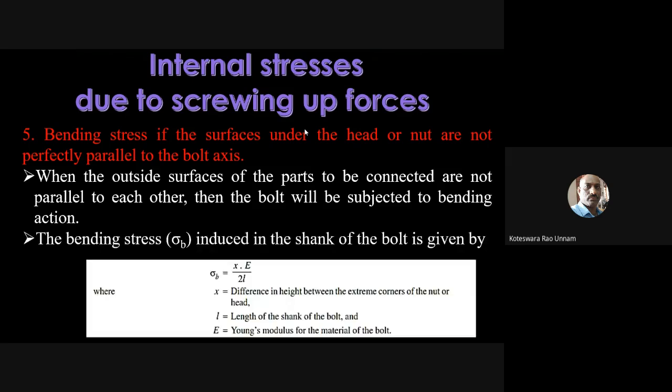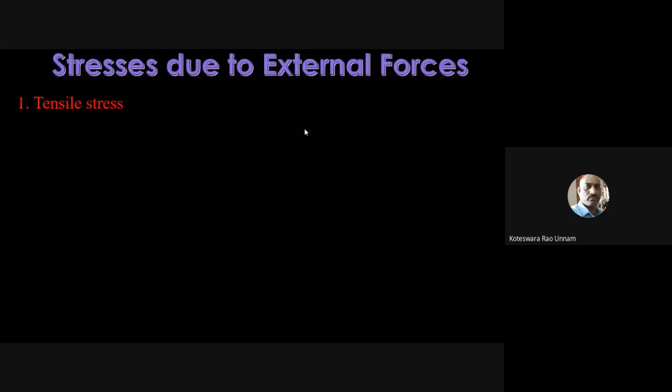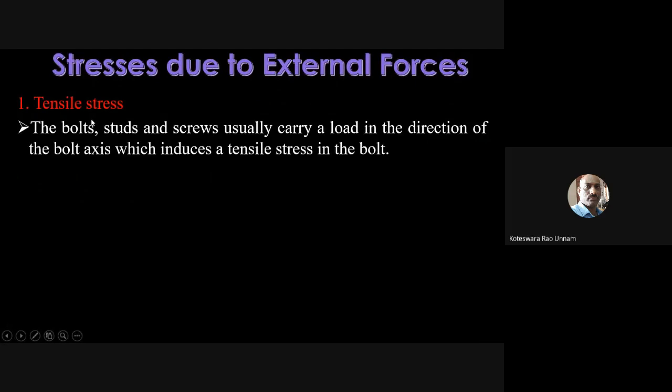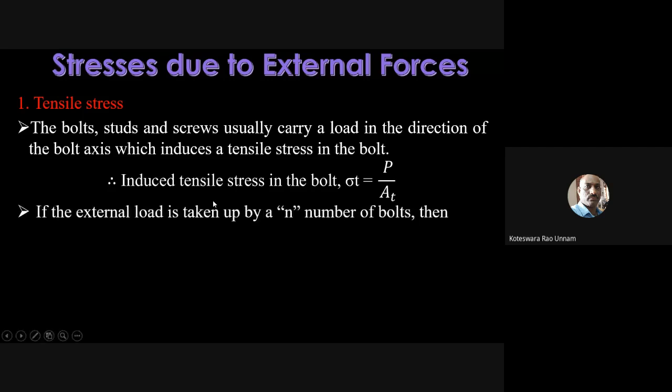Due to external forces, we have two types of stresses. One is tensile stress, the other one is shear stress. So the tensile stress is calculated based on the tensile stress area, and tensile load divided by tensile stress area is going to be the magnitude of the tensile stress.